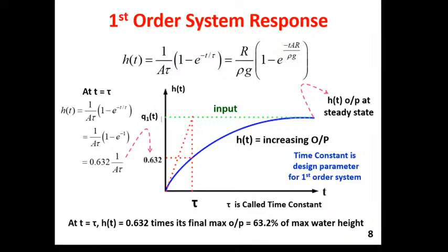It is not a strict rule, it is a thumb rule kind of thing. The time constant is generally found to be 1/5 of the total settling time. So, it is a thumb rule, please remember: 5 tau. For a first order system we generally do not speak of settling time. For the first order system there is only one system design parameter, that is the time constant. Okay. So, this is the explanation of the response.